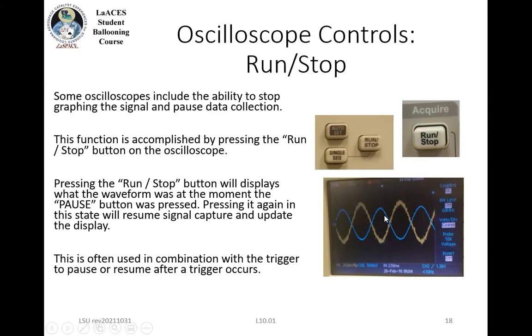So to be able to actually see what's happening, I have to look at it in 10-nanosecond chunks, and I want to look at the chunk that has the thing that I care about. So I'll set the trigger so that it'll go off on a particular condition that I want to capture. So that's sort of it for the time varying and tutorial for using an oscilloscope.